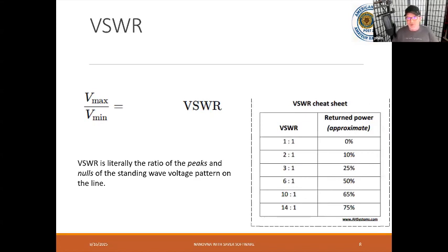And this is the last thing I'm going to say on this, from a cheat sheet point of view, we obviously want to get the maximum power transfer that we can. And we know that many modern rigs have antenna tuners that can try to kind of match things as well as they can. Ultimately, we don't want to bring too much power back to the transmitter because it will potentially damage the transceiver. But we know that modern transceivers will do something called foldback, where if they see too much power coming back, they will reduce the power going out.